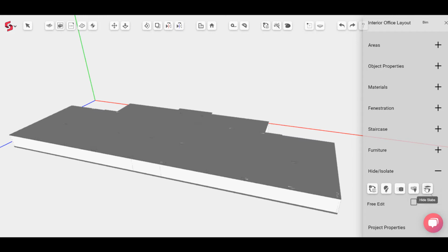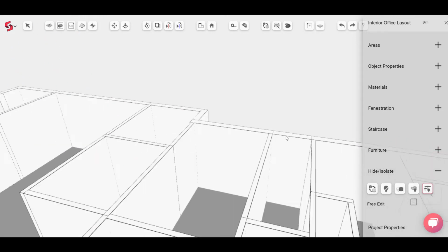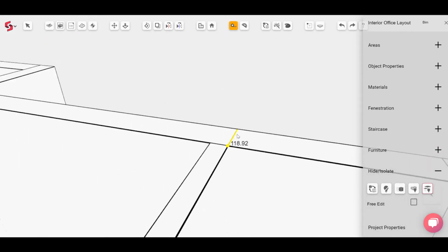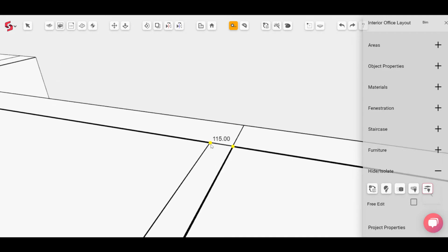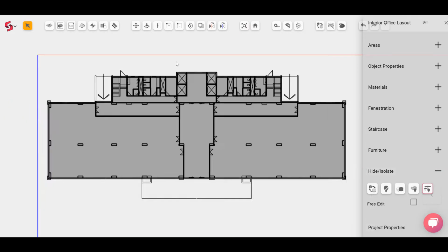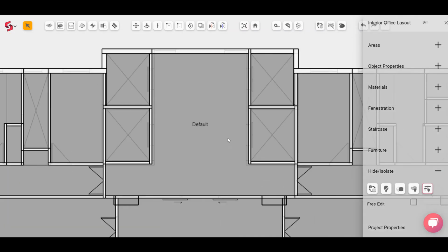You can hide and unhide the slabs, and as you zoom in, you can observe the different wall thicknesses that we had assigned earlier while drawing the spaces. Most walls, floorings, and slabs are created as you need, but there may be a few places that need to be tweaked. In areas around the lift, the walls created are not 230 mm.